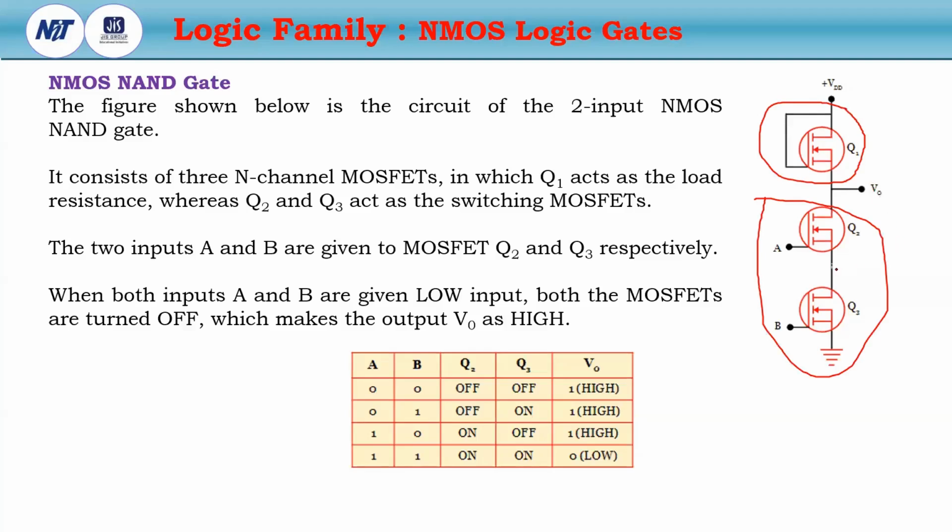So in the driver section, for designing the NAND operation, we first think of this as the AND. So the NMOS are connected in series in the driver section.